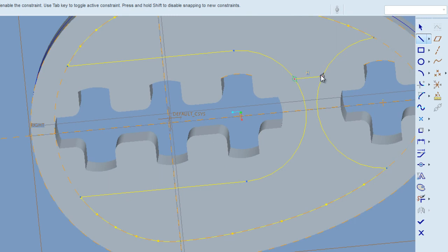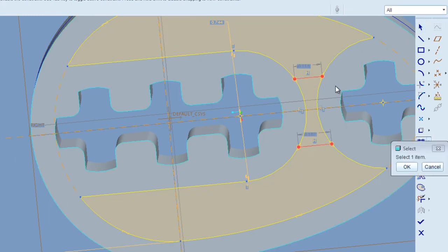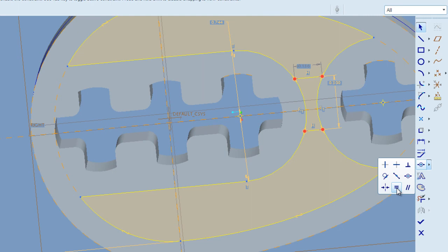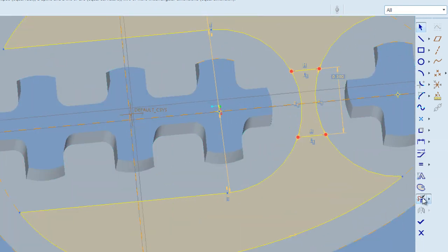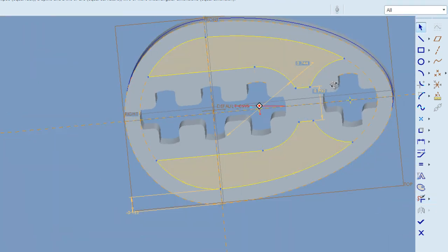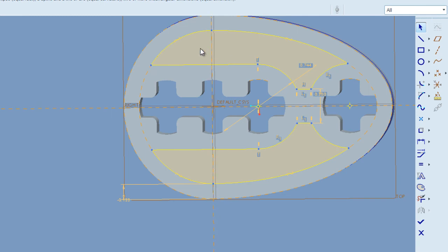And lastly, we have a sort of a bridge connecting these two parts, or these two circles. These are 0.3 units apart, and they're also the same length, meaning that we'll have these two lines centered with respect to the x-axis. Okay, so now we can just use the trim tool again. So we have the inner profile that we're going to cut away. Should be highlighted here.